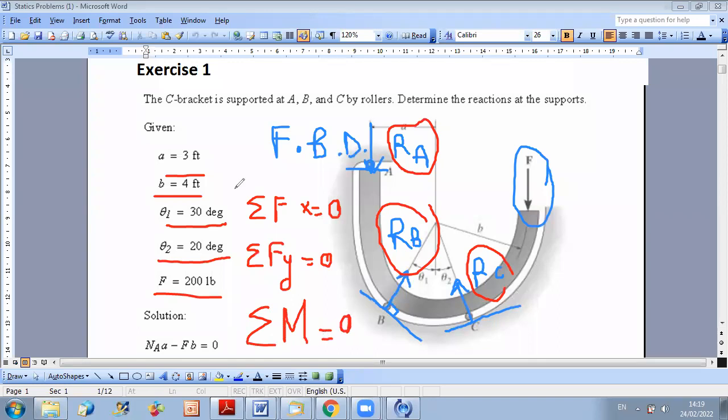And also, you can replace the force equations by moment equations if you want. But in general, force equations are easier to write than moment equations. This is why we'll use force projections, and we select one point in a way that sum of moment will give us a simple equation.